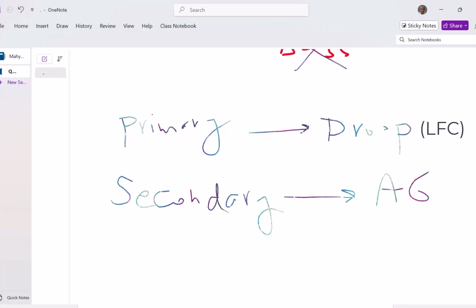And then we have a secondary control, which is the same as AGC, the AGC that tries to bring back the error in the frequency to 0. And that happens within a few seconds, up to a few minutes, okay? So that's slower. The primary frequency control is very fast, happens instantly. But the secondary control, AGC, is happening through ACE, and it takes a few seconds for the system, up to around a minute, to respond to that.